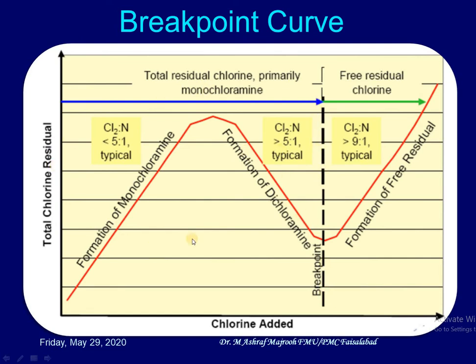Here the oxidation process of the nitrogenous compounds, the chlorine will be consumed and here it will appear as free chlorine. So this is the break point, and this green line will show the free residual chlorine, and these are the chloramines.